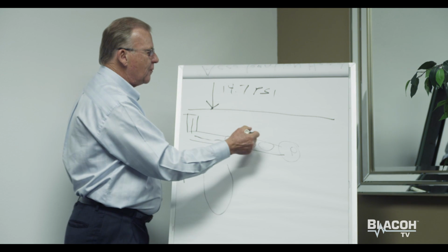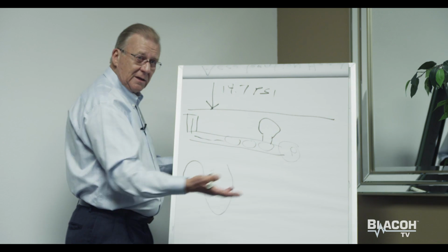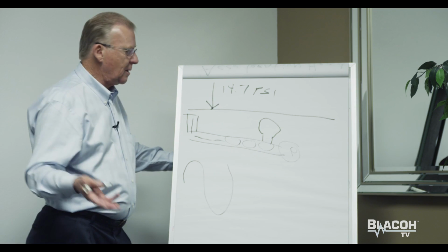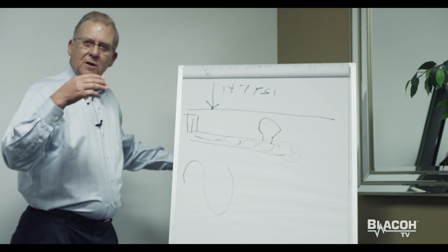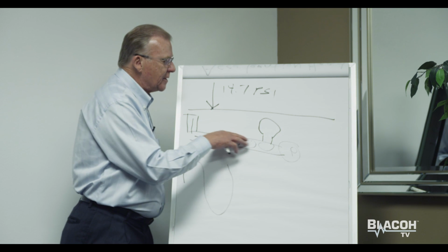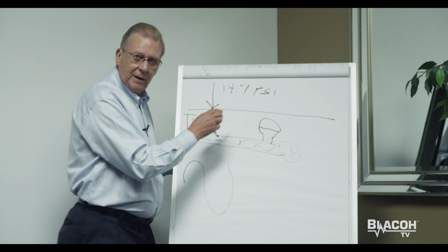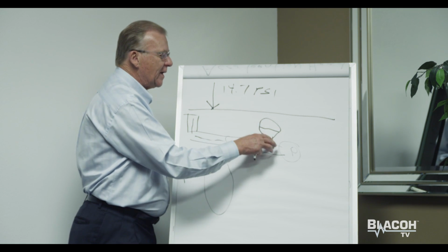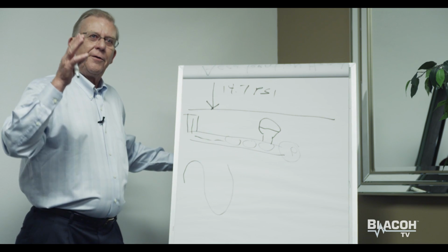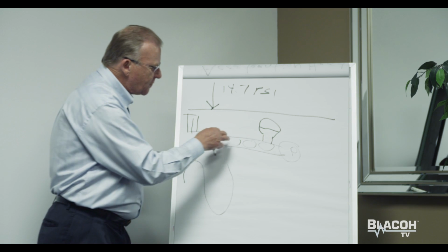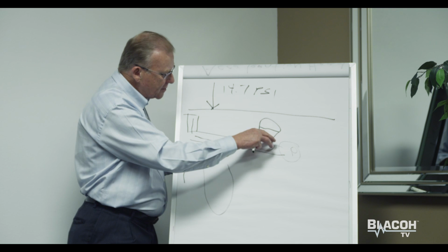If we were to install an inlet stabilizer here, and in some cases, depending upon that inlet pressure, actually put a vacuum in this. When the pump's valves close, this liquid is starting and stopping, but it will accumulate on the inlet stabilizer, providing a ready source of liquid right at the pump's inlet, so that during the shift, when this flow slows down, we've accumulated liquid in the accumulator or the inlet stabilizer.